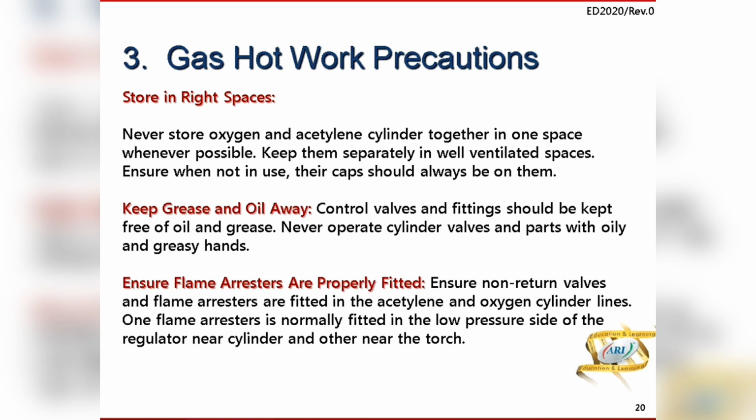So never store oxygen and acetylene cylinders together in one space. Keep them separate in well-ventilated spaces. Ensure that when not in use, the cap should always be on them. Keep grease and oil away. Control valves and fittings should be kept free from oil and grease. Never operate cylinder valves and parts with oily or greased hands.